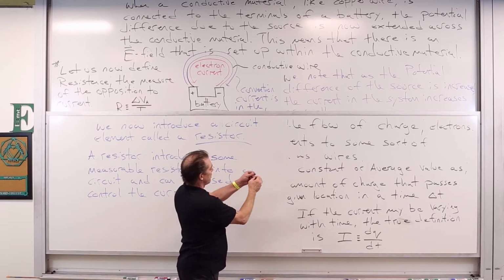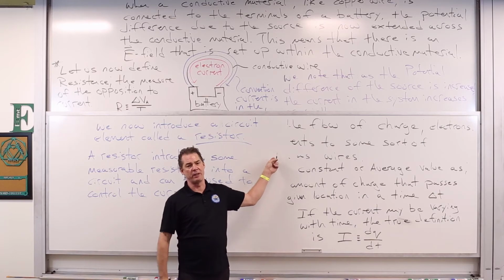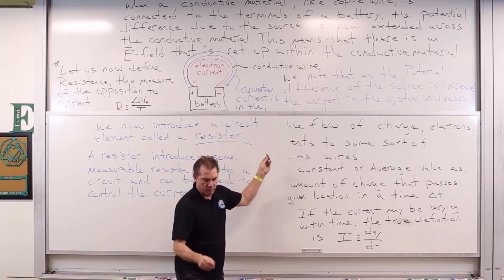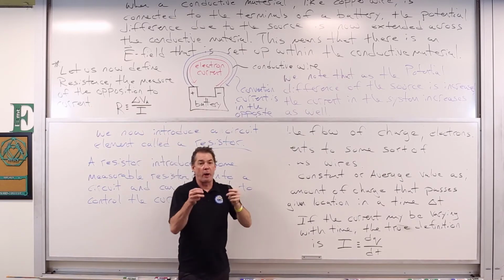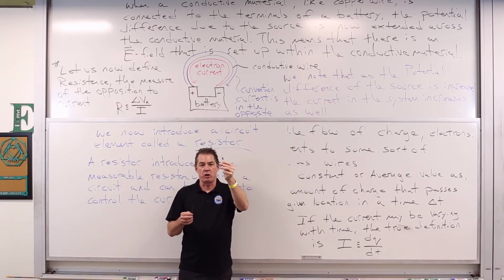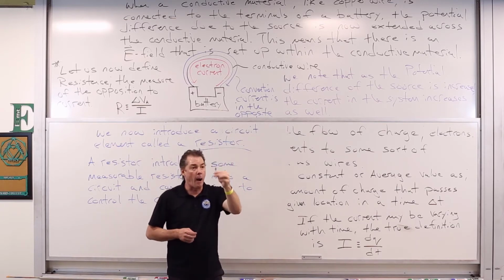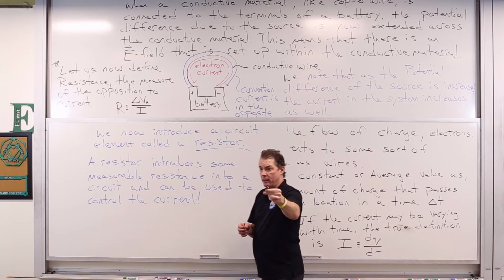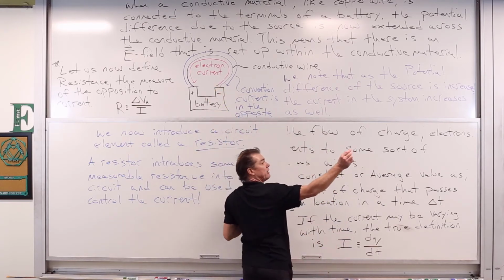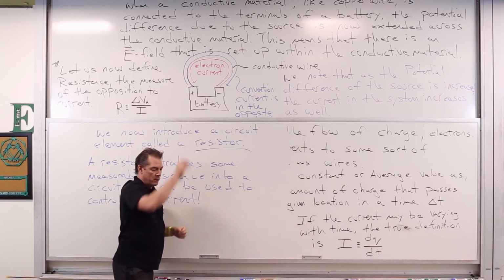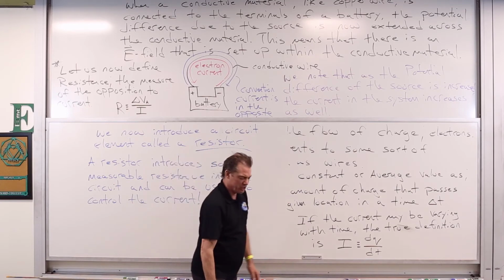You know, the ends are kind of curved up. That's okay, someone just bent those. This one has a resistance of 470 ohms. Which one, when hooked up to the same source potential, is going to allow for a greater amount of current? The resistor with the least resistance. This one produces a lower amount of opposition to current, and thus the current will be greater in the circuit if I stick it in here than if I stuck this 680 ohm resistor in. So lower resistance, greater amount of current is a general rule there.